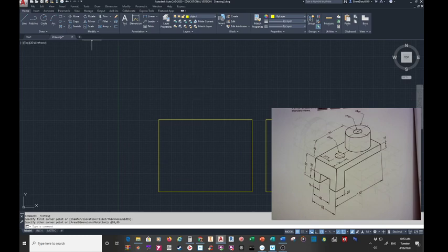Now my top view, I'm going to do the same thing, picking up a rectangle, hover, move up, pick. This one's going to be 110, comma 55. Okay, so this is the area that my views take up.